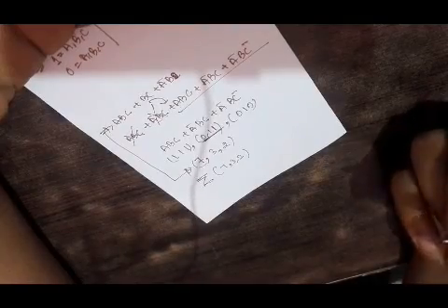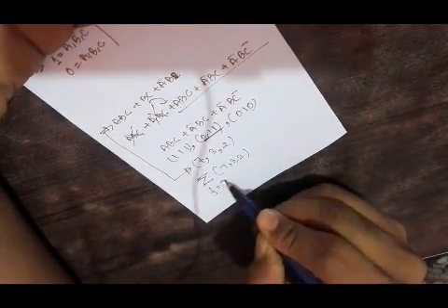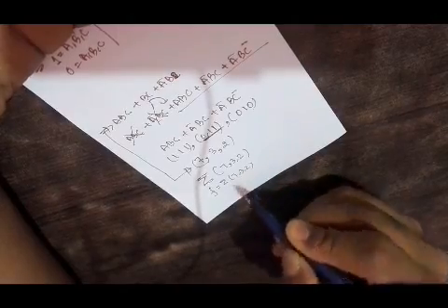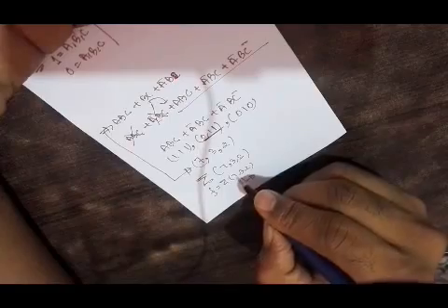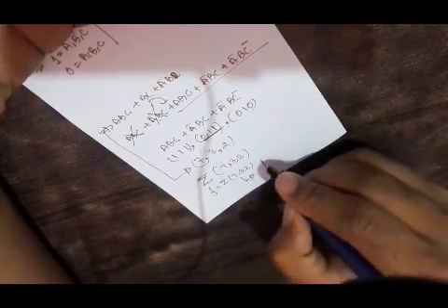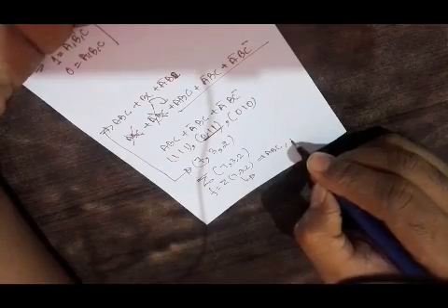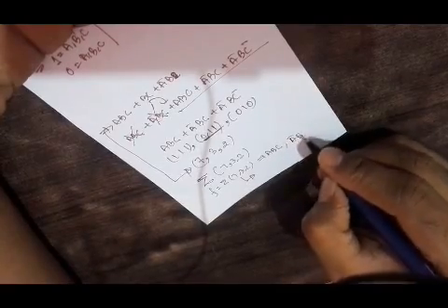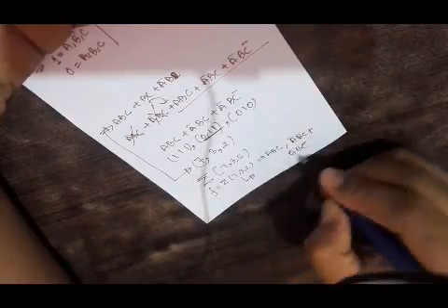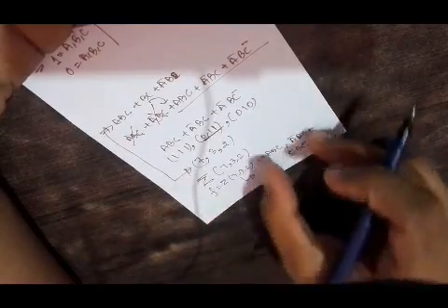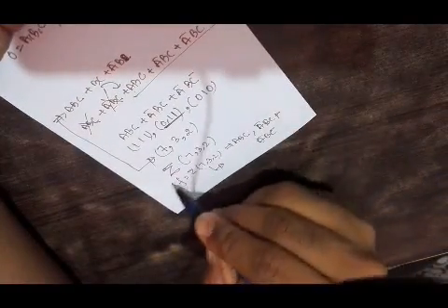Similarly, if we have an expression where function f is summation of 7, 3, 2, we will use the k-map, or we can directly write this: 7 means A, B, C, 3 means A bar, since A is 0, B, C, and 2 means A bar, B, C bar. We can directly convert into this expression, and this expression and that expression mean the same. Both are equivalent.